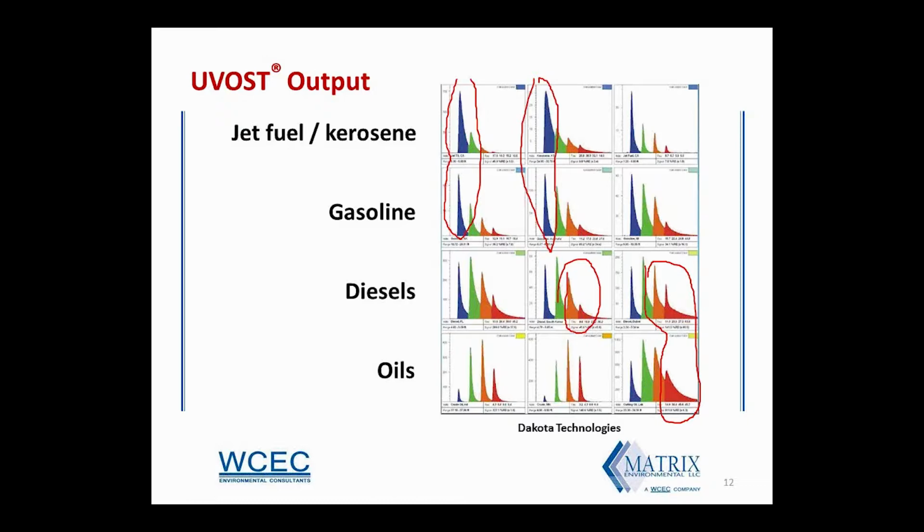sources at a site. And LNAPL samples obtained from monitoring wells on a particular site can be placed directly on the UVOST before mobilization or during the course of the field work, and that allows us to check the instrument response and the characteristics of that specific material. So that's a pretty handy thing to do. We usually recommend that people send us in some of their product before we schedule a site if there's any question about its ability to be examined with this tool.